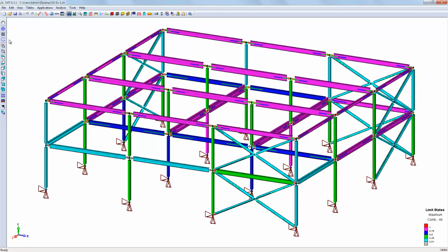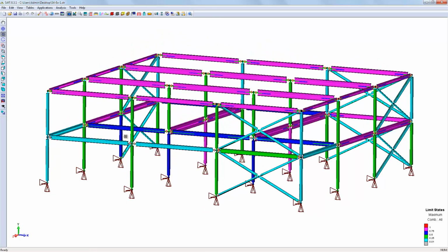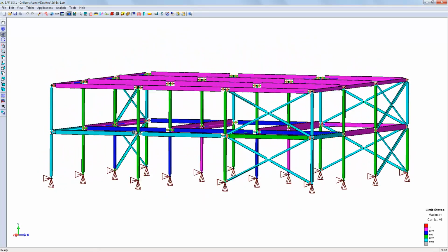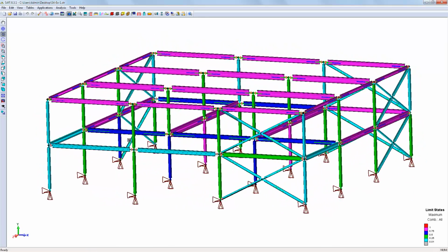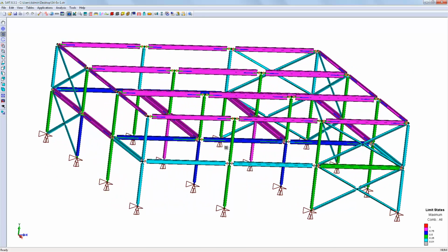The Orbit command rotates the view of the structure in the space. The rotation is made around the screen's X and Y axes according to the center of the screen, the rotation being determined by the screen center and by the movement of the mouse. Click on the Orbit button to activate the command. You may rotate the view by clicking on the structure and by moving the mouse while keeping the left button of the mouse pressed. Release the mouse button to end the rotation.